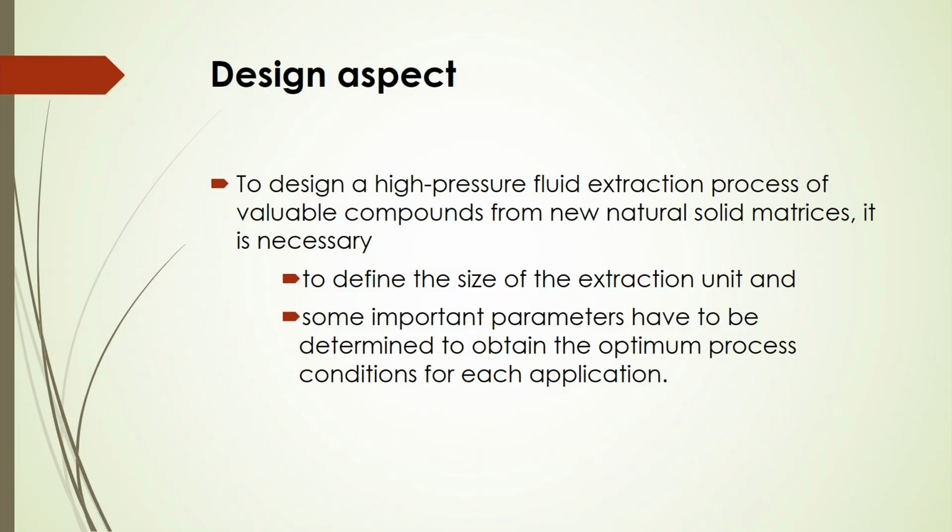So, you have to define the system in such a way that the size of the extraction unit is minimized, and also consider parameters like mass transfer, solubility criteria, packing materials, and whether channeling and flooding conditions exist or not.